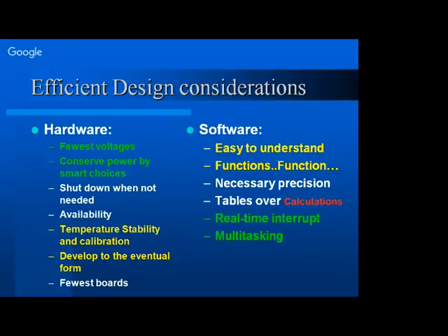The overall cost of the PCB and the components increases, and the reliability goes down as soon as your components increase. So you have to be very wise in the selection of the voltages that you use in your application, because these days if you use a single-voltage based application, your cost will definitely come down, because LCDs are also available for 3.3 volt. So you have to be wise while you make selection of the components and the voltages that you will be using.